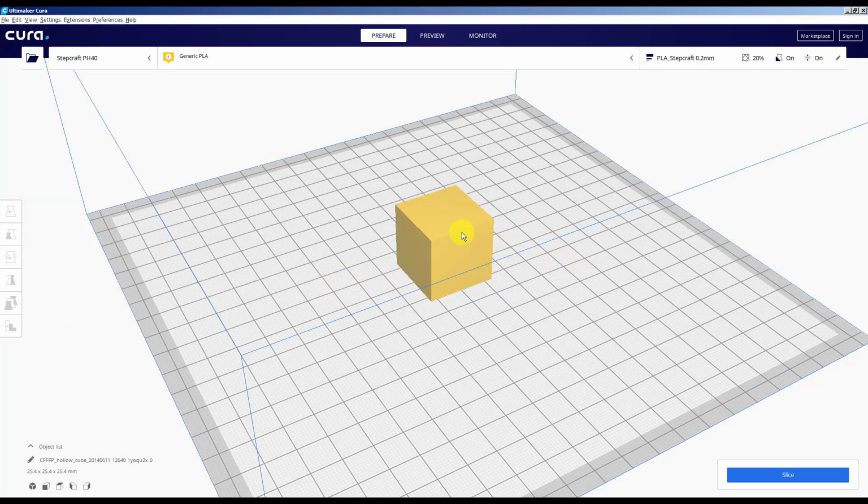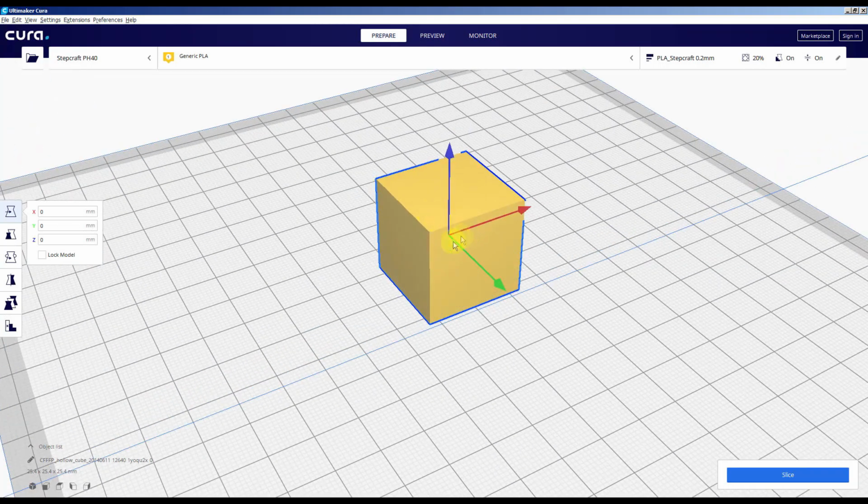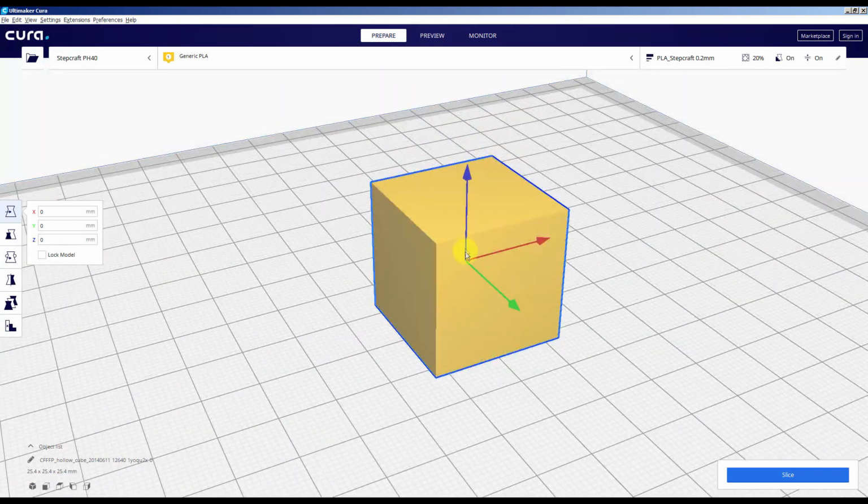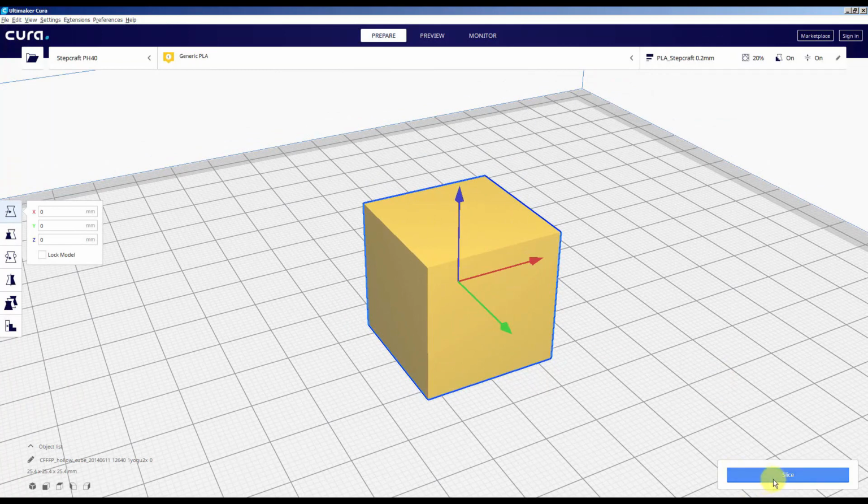So how do you make the G code? It's super simple. After you load the object, you only press this button, slice. It processes the slicing, and that's it. It would take 58 minutes approximately. It requires 2.49 meters of material and 7 grams of filament.